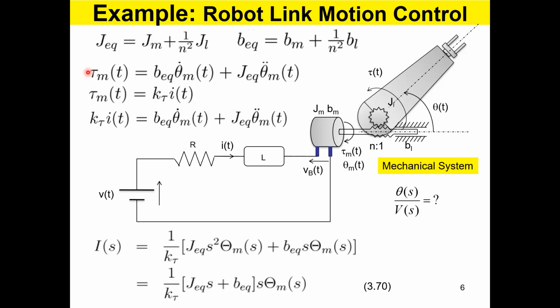You can't draw as big a current as you get initially, because the back EMF reduces the actual voltage applied on the motor to drive a current. So all in all, this is going to saturate at some point, and after that there won't be any acceleration, and the entire torque generated will be used to maintain the speed.